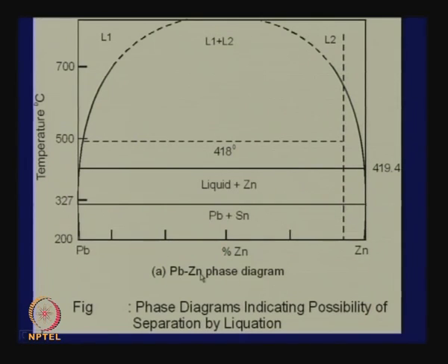This will be of great importance in understanding what is done in the lead zinc blast furnace, where we would find a way to recover zinc vapors. Now, in a blast furnace, lead is produced at the bottom by smelting operations. If lead ores also have zinc, zinc vapors will go out. They are dissolved in lead at a higher temperature, and then that lead is cooled, so that zinc comes out of the lead